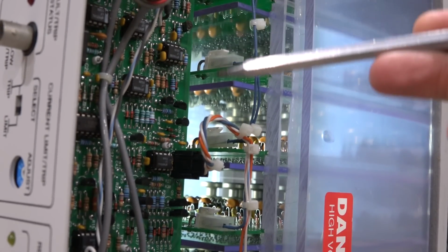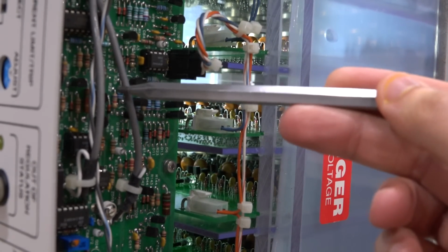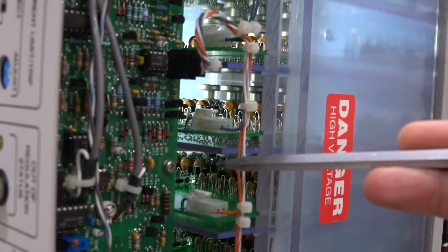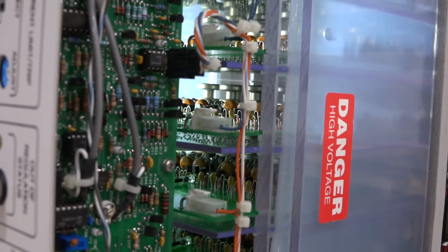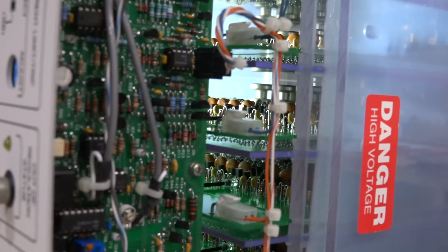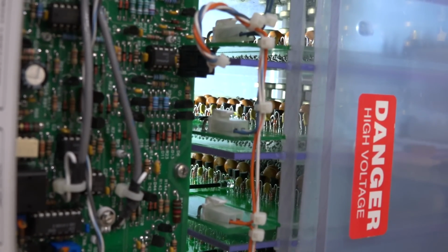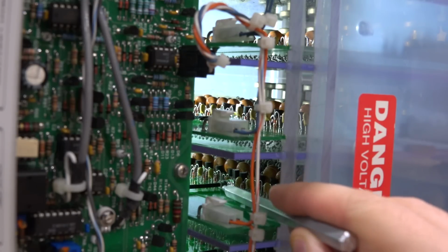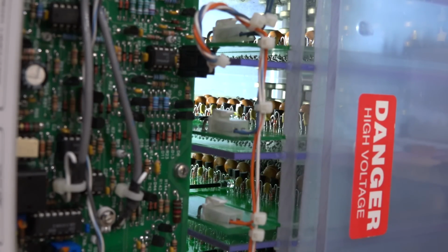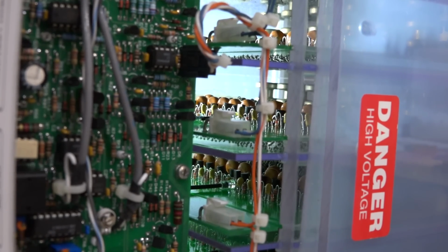So this cable in the front connects to the low voltage side, which is this port over here. Now they need to get this and couple it somehow into each of those high voltage stages and then appropriately divide the signal to be able to drive the final stage. And as I mentioned, they cannot do that galvanically. So if you look carefully, you can actually see that there's a little LED in the back and there's a light pipe. And they're using that light pipe to basically send the analog signal over. And all of these diodes vertically have a certain offset associated with them, so they all drive these stages simultaneously with the appropriate offset voltage.